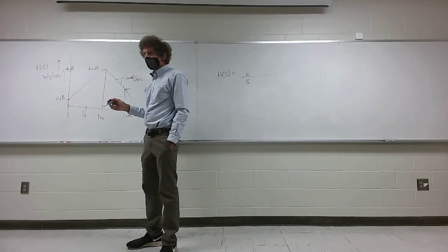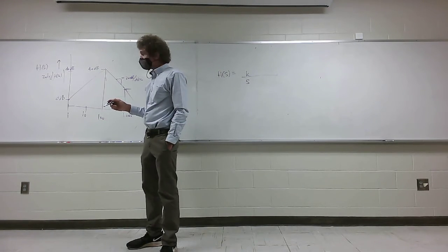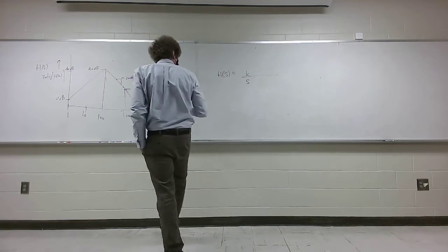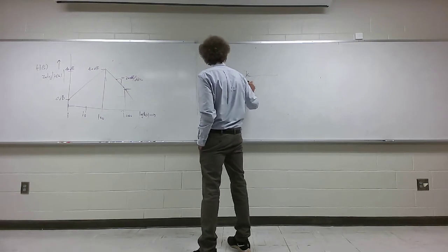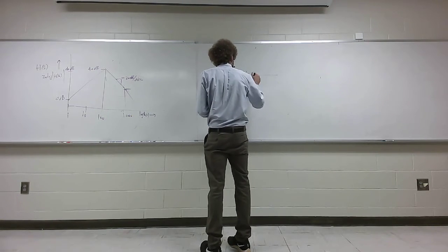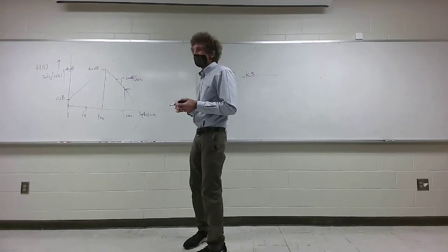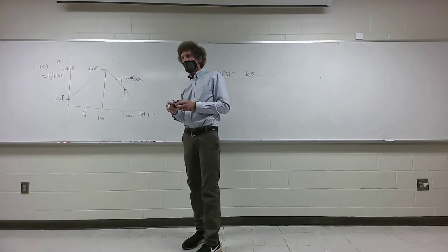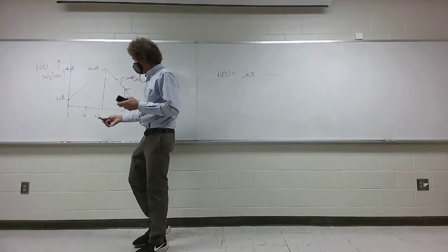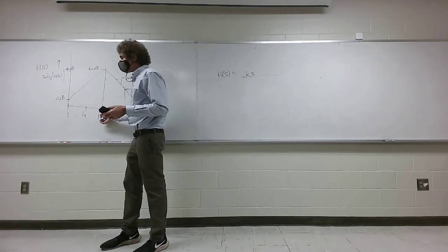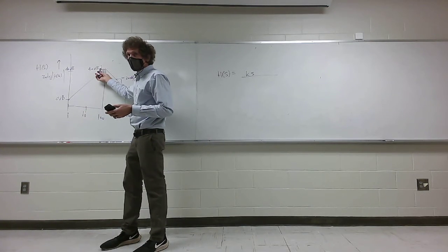Now, for positive slopes like that, that's a zero. You're absolutely right. I'm sorry, I reversed this. This should be an S up here. That was my mistake. This is coming up. So, by the way, I tried to make it go 2 orders of magnitude, 40 dB. That means that's 20 dB per decade. So it's S to a single power, right?